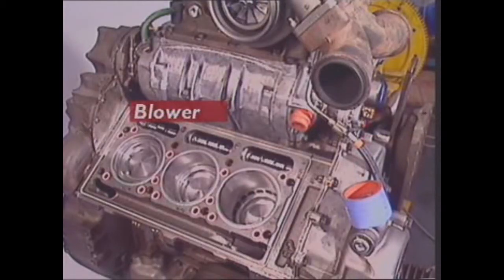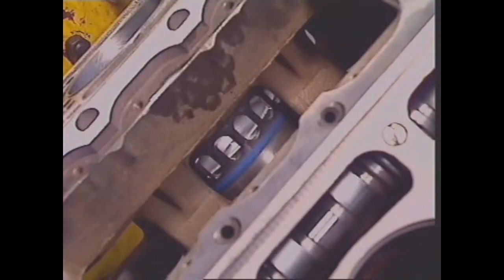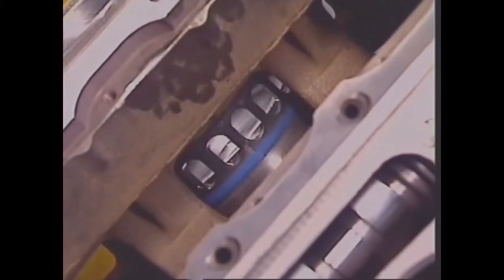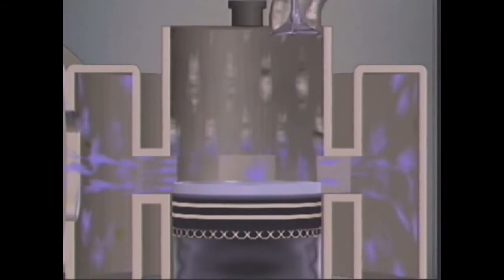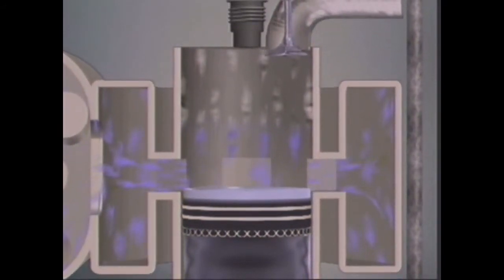In a 2-stroke diesel engine, an air pump or blower provides clean incoming air at pressure slightly above that of outgoing exhaust gases. The blower delivers air to an airbox surrounding the cylinder. When the piston uncovers the inlet ports, air enters the cylinder through a number of them around the cylinder walls. This fills the cylinder with fresh air and helps blow out exhaust gases. Removing exhaust gases is called scavenging.